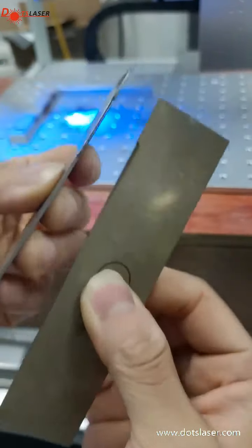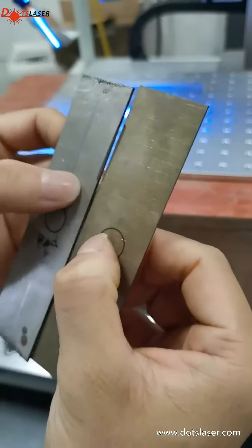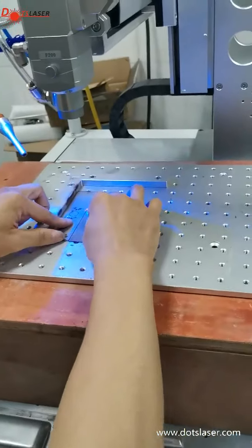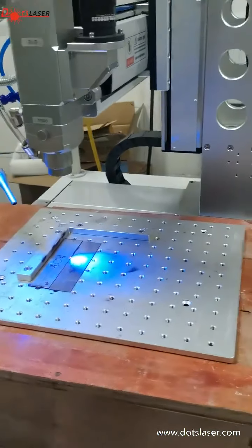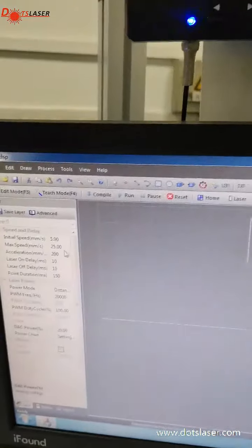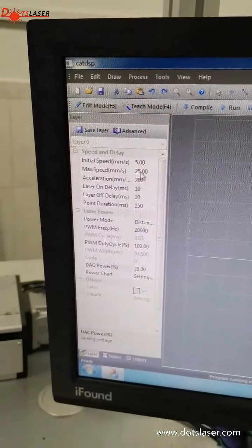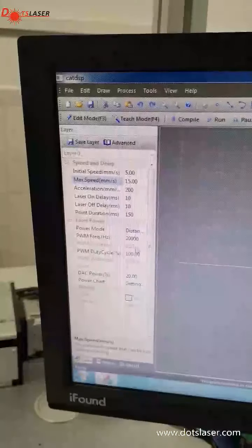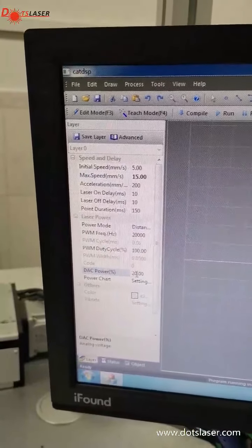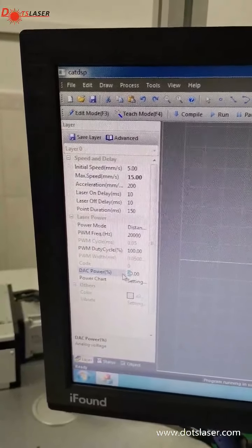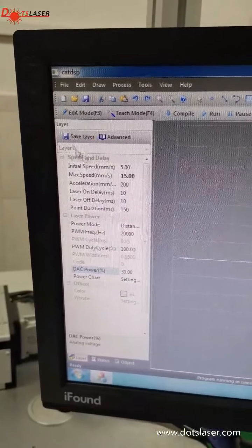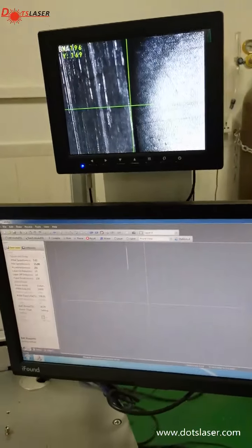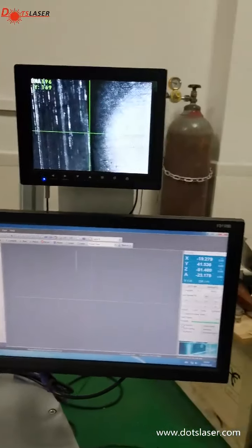If the welding is not very tough, so we need to make a little bit more power. So we add more power, reduce the welding speed. We reduce the welding speed and raise up the power to 30 and then save it. Alright? So simulation.